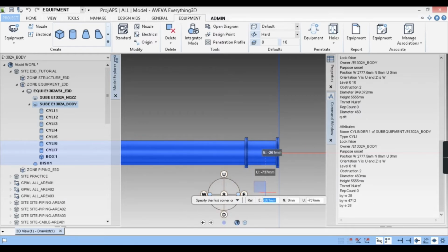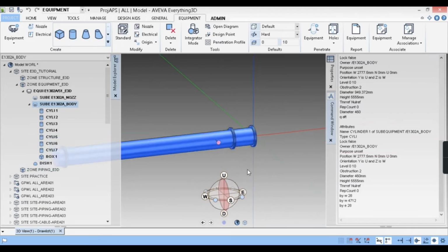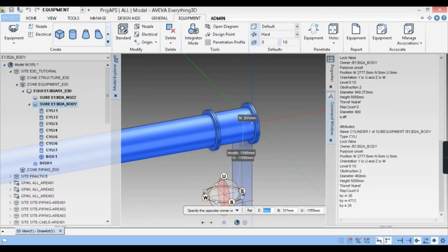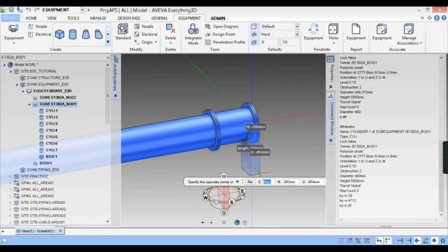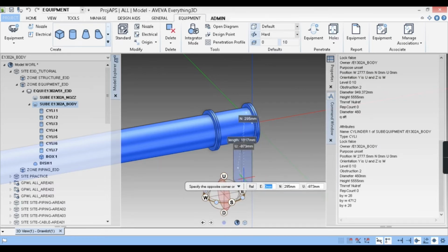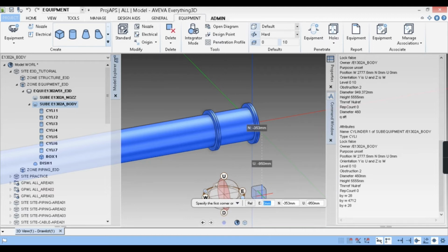and from there I'll move it to the required place. So first point will be 0 tab 0 tab 0 and enter. Now I'll just rotate it, and now it is asking me the second corner. So for example, by mistake, if you have entered the wrong values in the first corner position, and if you want to re-enter it, just click the down arrow, not here, I mean the keyboard down arrow, and you'll see this tab, and click on that tab, and you can re-enter those values. So again I'll enter 0, 0, 0.